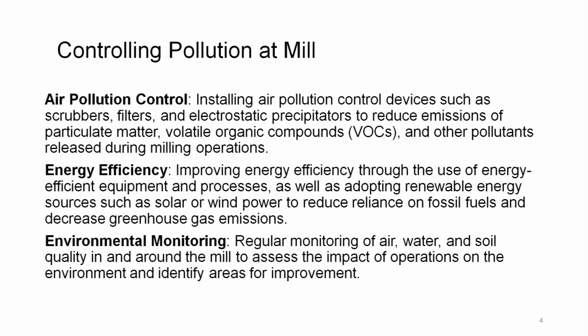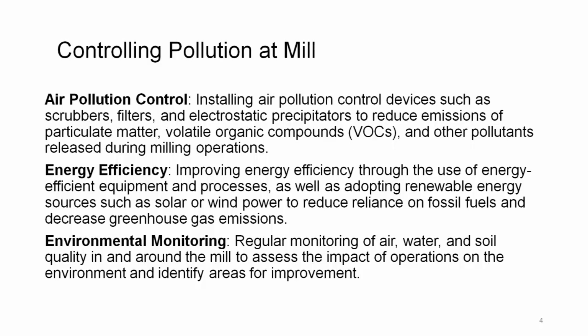So, during the milling process, seen or unseen, there are a lot of particulate matters and a lot of volatile organic compounds, VOCs, which we cannot see with our naked eyes, but they exist and they also need to be controlled, and therefore, installing an air pollution control device is a must.